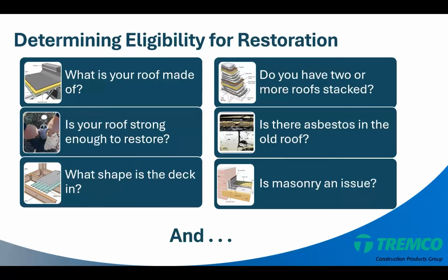And then also masonry. Not only in exterior walls, but also in parapets or chimneys or other aspects of that entire building envelope, tuck pointing or masonry, and even just the porous materials, can be an issue or allow water into the system. In fact, many times we find that what's considered to be a roof leak is actually coming from an exterior wall or another component within the roof system or the building envelope.